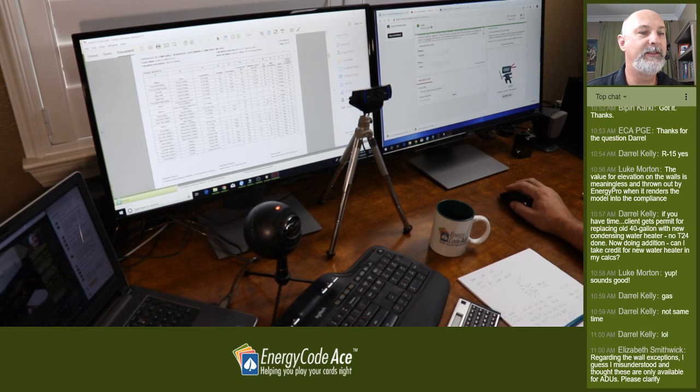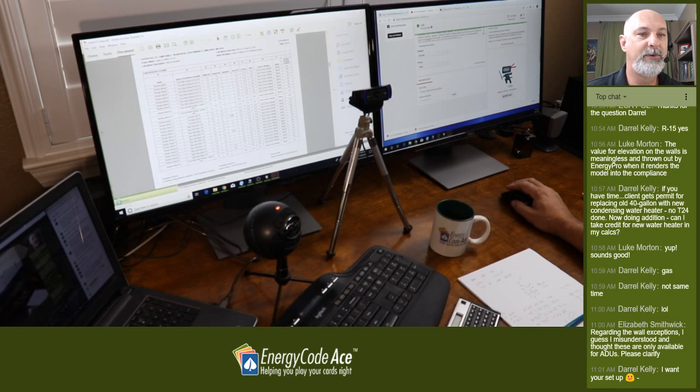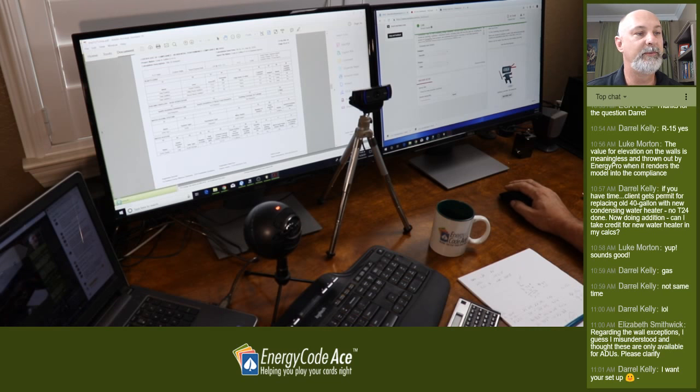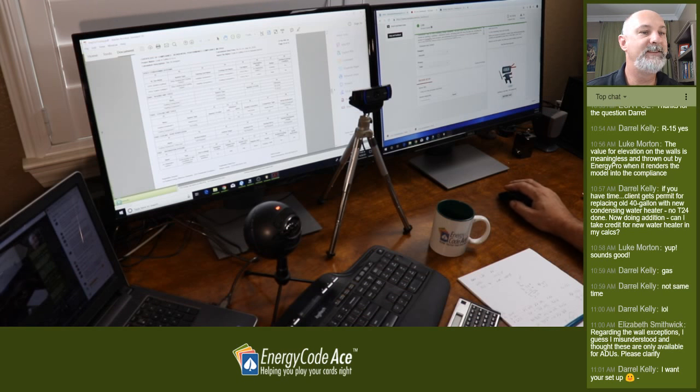We could go in and verify all these areas, go into our fenestration, verify that we have all of our altered windows, all of our new windows, our opaque doors. This is the table for overhangs. It's quite exhaustive because I added a lot of those. Here's my opaque surface construct tables. I could verify that all my construction assemblies were modeled correctly. And then my slab, and then it goes down to my mechanical system. Hot water is existing. My HVAC system, one of those is existing, one of those is new. Here are my efficiencies here. So good.